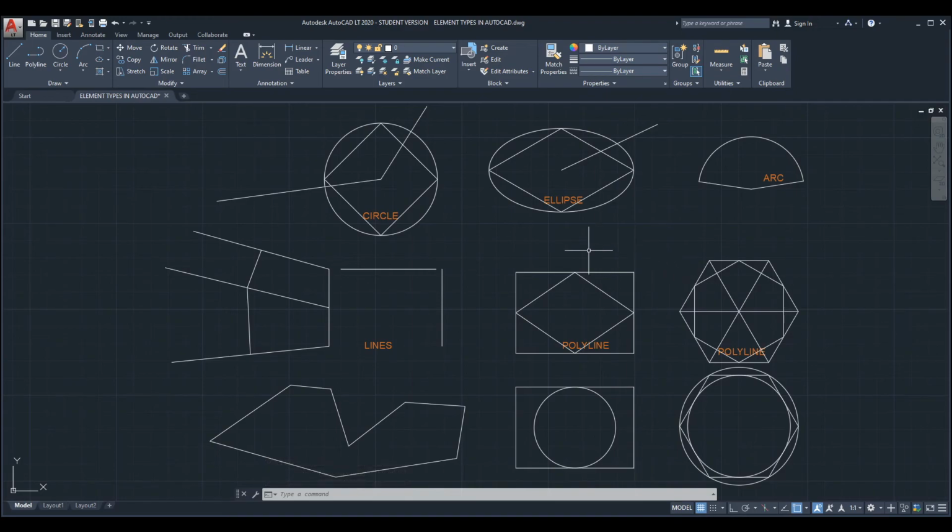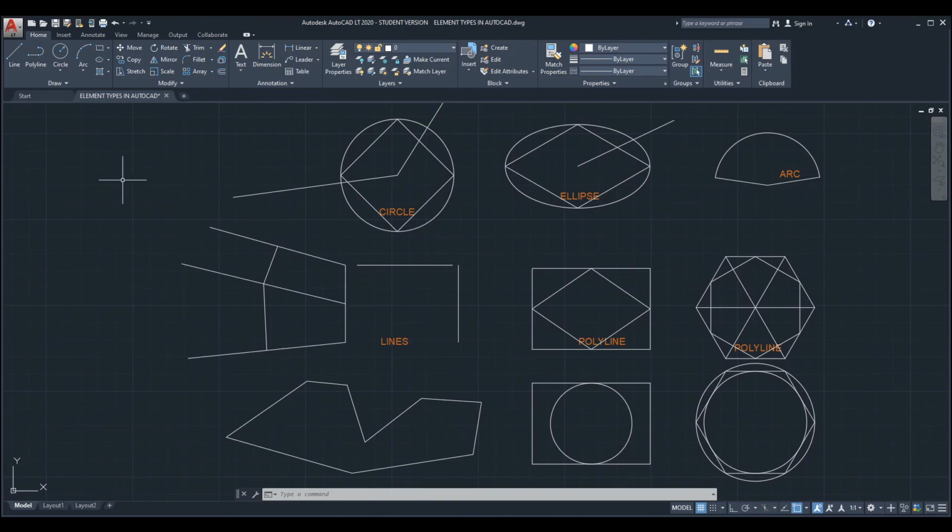All right. And the next one I want to tell you is the intersection snap point. So intersection, and there's also apparent intersection. You would want to turn these two on together. An intersection, basically, is that any time any geometries cross each other, you'll be able to reference the point where they meet. So if I have a line that literally crosses all of these lines right here, we will have an intersection point here, one here, one here, and one here. And then you can see we will get a green X sign that represents intersection.